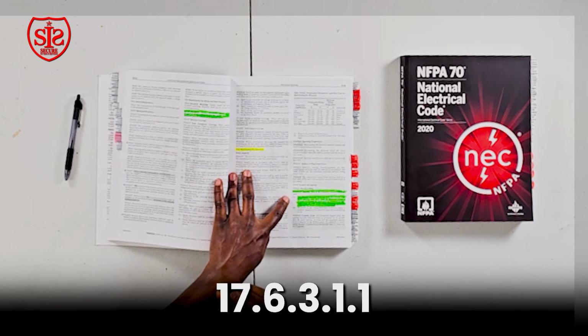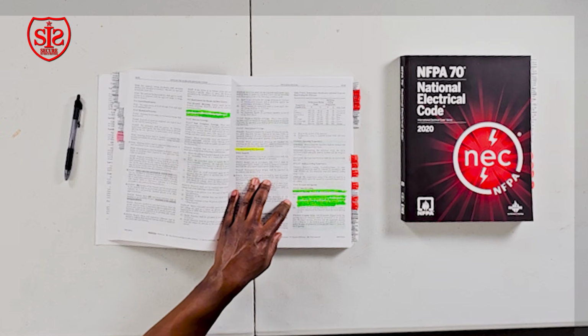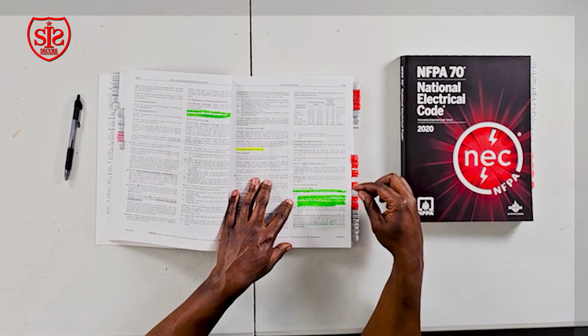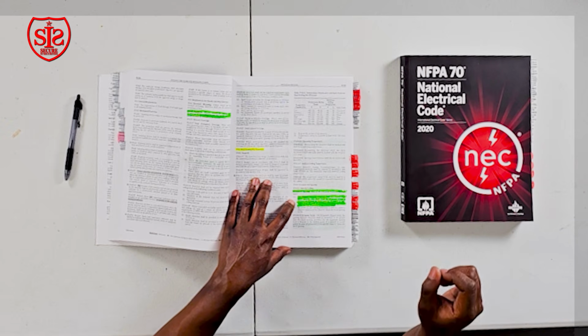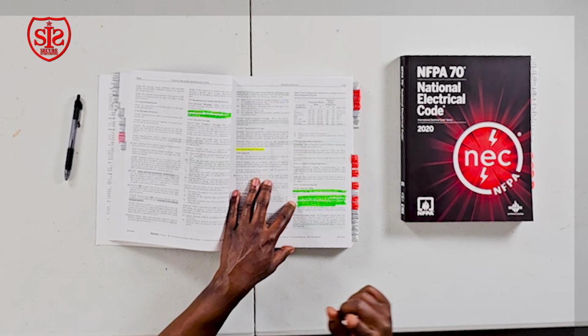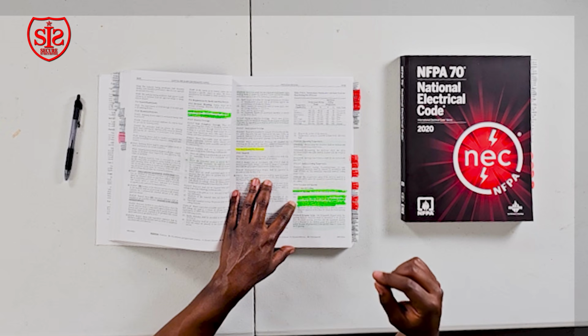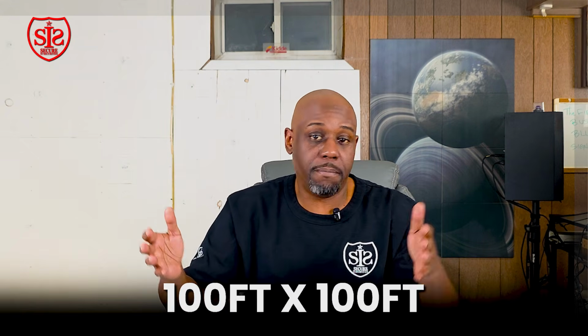Now, another code reference you should know is 17.6.3.1.1, and this is about spacing. One of the following requirements shall apply. The distance between detectors shall not exceed their listed spacing, and there shall be detectors within a distance of 1/2 the listed spacing measured at right angles from the wall or partition extending upwards within the top 15% of the ceiling height.